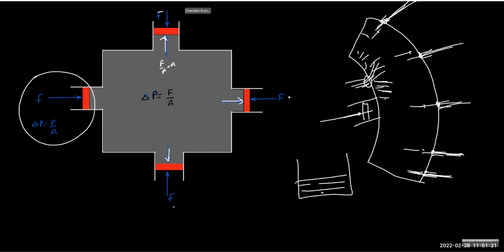Normally, when water comes down from a tank, the pressure is rho g small h, because it is a small h. But in the closed tank, we can fill in more air to create extra pressure. Therefore the pressure here will be rho g h plus the pressure that we create through air pressure, and therefore the water will leave at high speed. This is how we create the pressure.